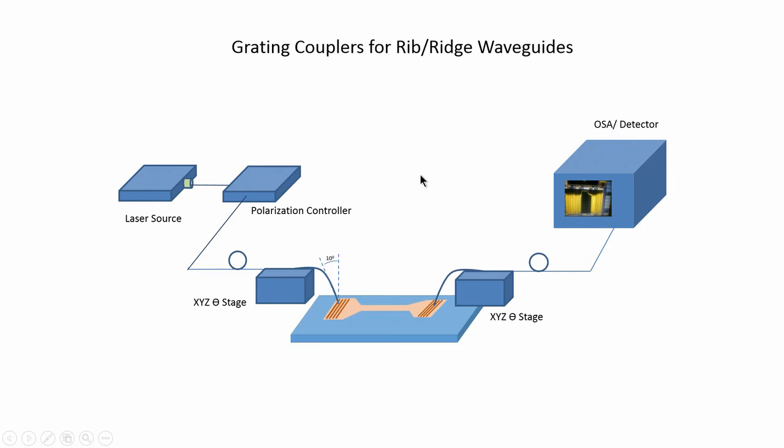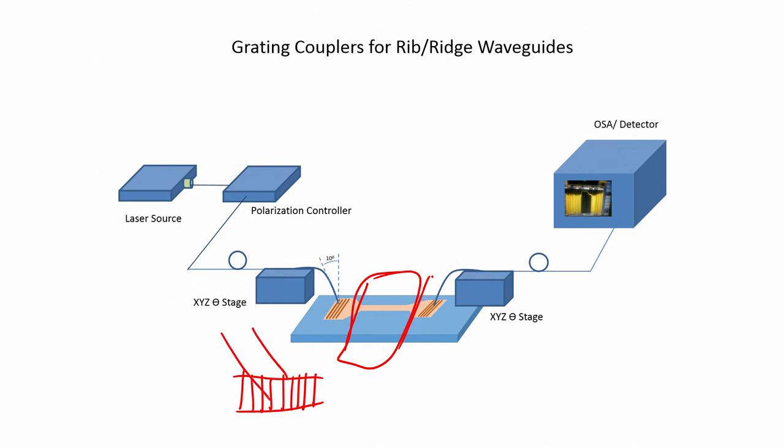So, this is another new process which has become important recently, called the grating couplers. On the same wafer where you have the optical circuit, you create waveguide gratings. Waveguide grating, as we have seen, is a periodic variation of the refractive index, and it is possible to work out when light is launched from an optical fiber onto the grating, the light could be coupled into the optical waveguide. So, the light coming from an optical fiber falls on the grating and couples into the photonic integrated circuits.